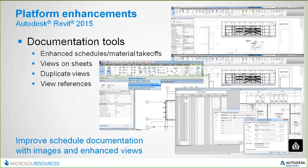When you are switching back and forth between your active view and a sheet, and you want to deactivate the view, now instead of right-clicking to deactivate the view, you can actually double-click outside of the view to deactivate it. That was actually one of the wish list items that Autodesk has provided us.